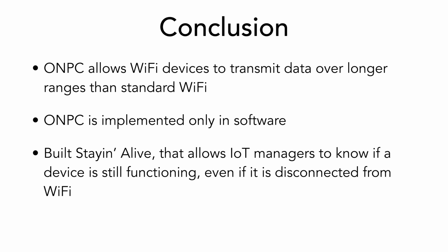Or it'd be kind of cool, they call it cross-technology communication, where a Bluetooth device communicates with a Wi-Fi device or vice versa. This would make it possible now because we're just looking at energy. We're just transmitting out energy and looking at energy. That's all we're doing. We're not actually trying to decode the frames. And so there doesn't have to be any kind of acknowledgement of what kind of modulations you're using.